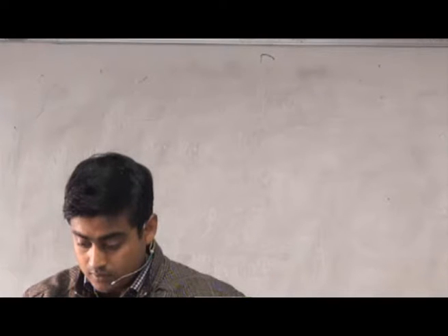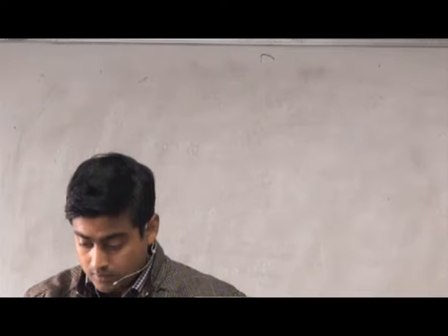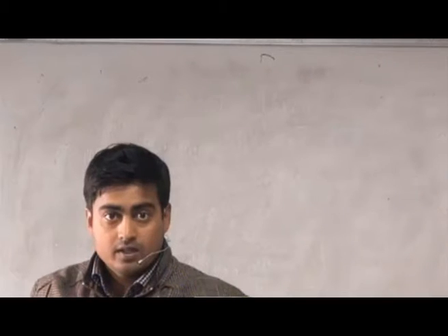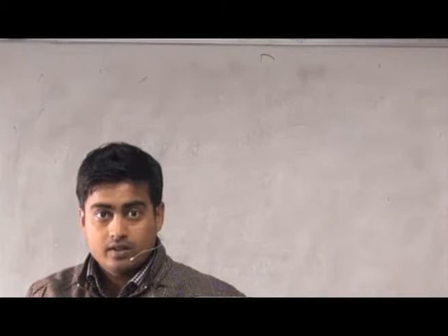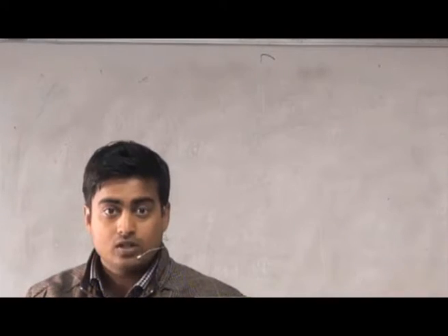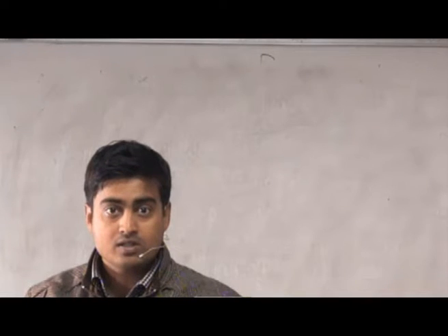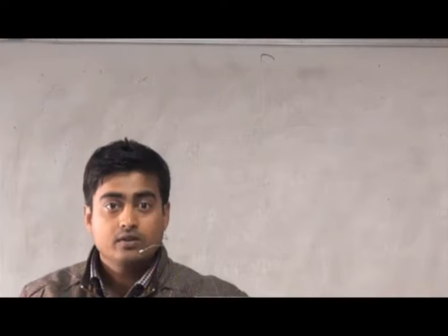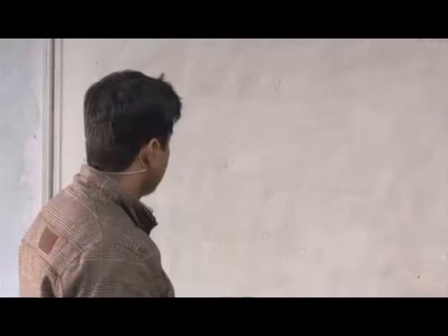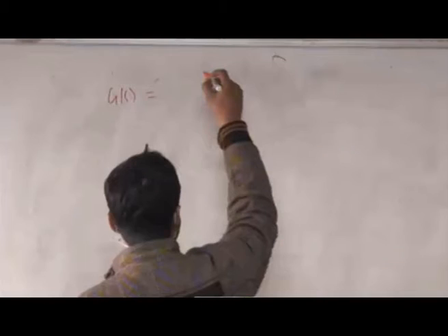First of all, you need to understand that whatever transfer functions we have considered here are frequency domain representations. When we saw in the very first session the interrelationship between all the representations of the system, there we had the transfer function, state space, impulse response, and the frequency response. This transfer function is basically the frequency response which we use for time domain analysis. So, seeing this transfer function, how can I approximate this higher order transfer function to a FOPDT system?